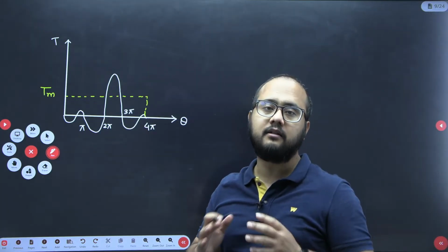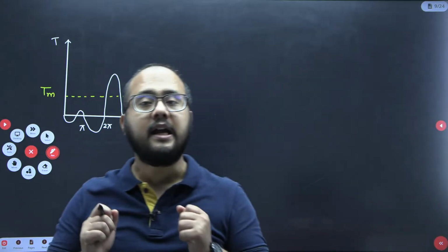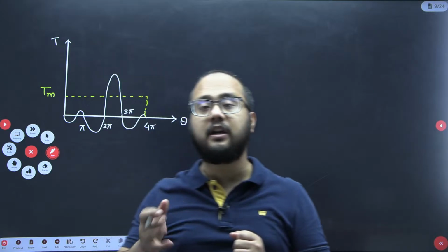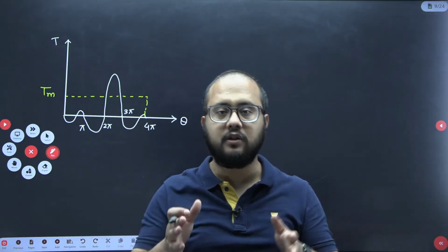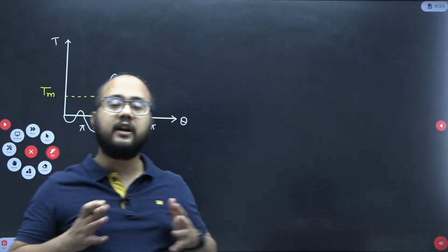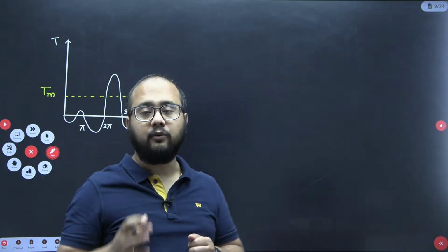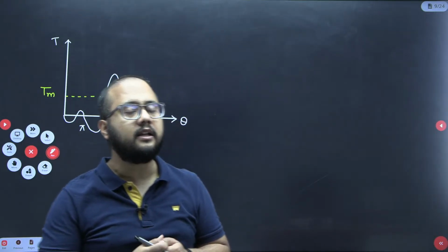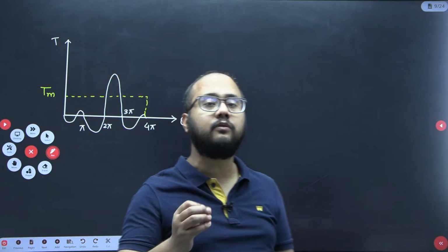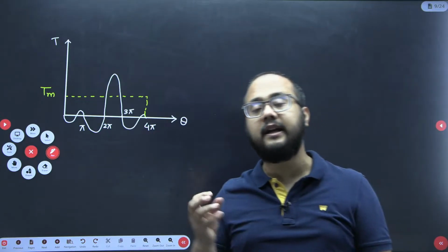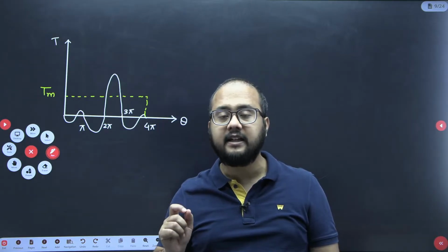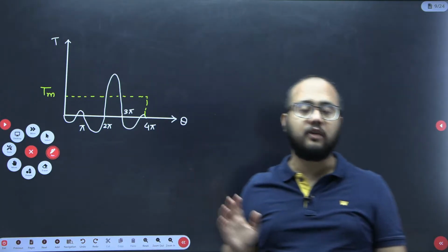Engine is going to accelerate, because whatever torque we are developing is more than the required value. Now if the actual torque value is less compared to the mean resisting torque value, in that case retardation is going to happen, right?